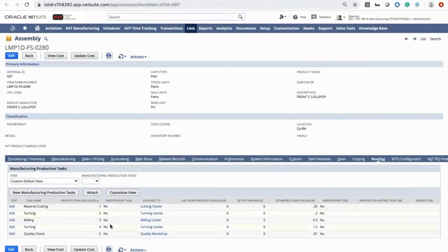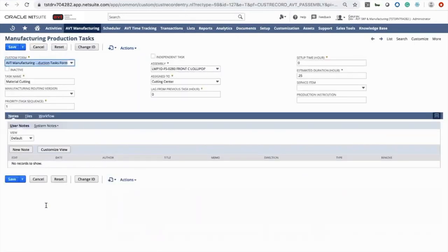It might be some cutting involved, some milling, turning, and you might set up a route over here, and the route will determine what steps are involved and in what sequence. It's especially important in a production environment where you want to take the product through a number of work centers, being loaded onto different areas of the factory. Here, you can simply put in a sequence.